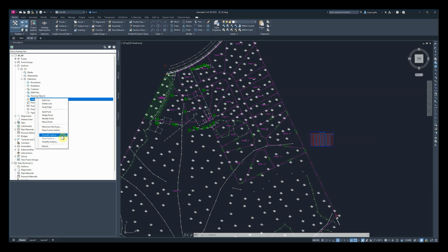And then smooth surface, again, just because of the potential faults of a generated surface, we could end up with overlapping features or contour lines. Smoothing the surface is going to utilize some statistical methods, either natural neighbor or a kriging model, in order to smooth that and prevent any kind of overlap. It is important to note that when you smooth the surface, the tool is going to create additional points that didn't already exist in your surface to allow those contour lines to be drawn without overlap.